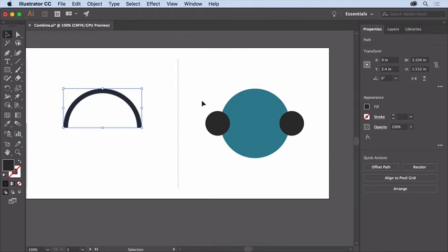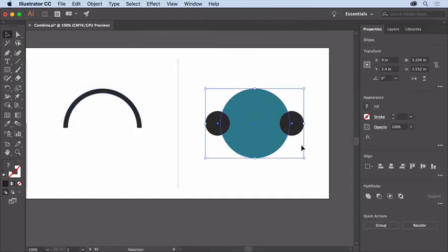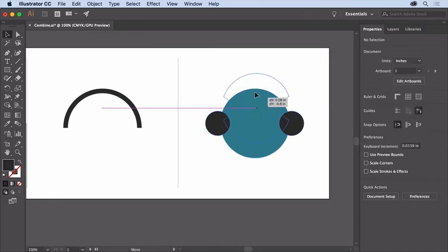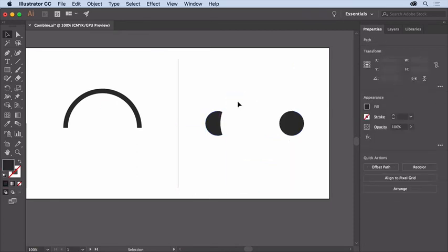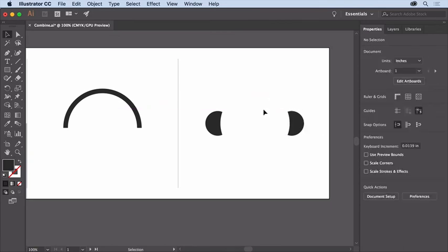Now the three circles over here, they're supposed to become the earpieces for the headphones. So drag across those shapes to select them. Click More Options in the Pathfinder section of the panel. Now we can't choose Minus Back because the circle in the back would only be removed from one of the circles. So click Divide to divide the shapes where they intersect. Then press the Escape key to hide the panel. Since applying Divide creates a group, click Ungroup to access the individual objects. Then you can drag and even delete these shapes by pressing Backspace or Delete. You can actually see how it's divided them up.